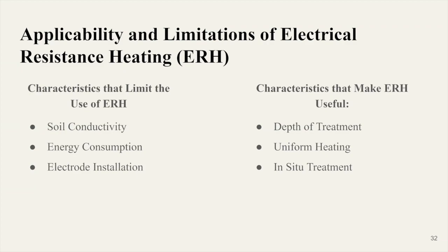Energy consumption, since ERH requires significant energy inputs to sustain elevated temperatures, leading to high operational costs, particularly for larger or deeper contamination zones. And lastly, electrode installation. The installation of electrodes for ERH can be complex and time-consuming, requiring careful planning and expertise to ensure proper placement and configuration. The characteristics that make the method useful are the depth of treatment as well.